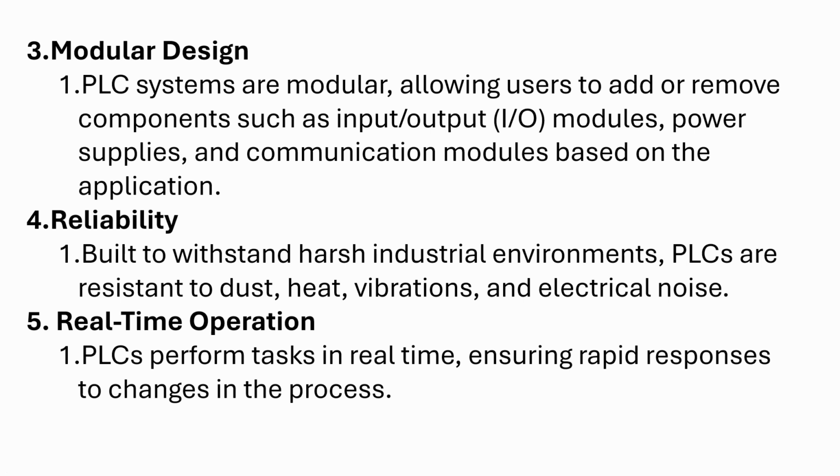One thing about PLCs, they have a modular design. They're modular, which allows users to add or remove components, such as input and output modules, power supplies, and also communication modules. A lot of the PLCs now communicate over Ethernet. There's lots of other communication protocols, but ones that are based on Ethernet are most common today.